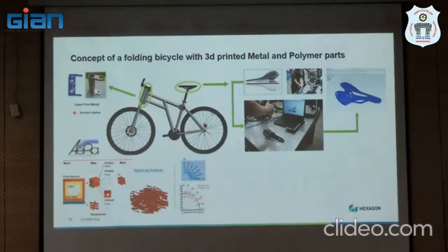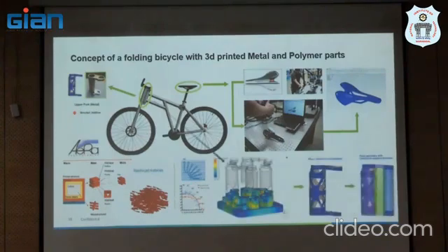But for metal, still a lot of justification has to be provided. For composite, it's very easy. You know the unidirectional and bidirectional strength. You can develop your own composite material based on the application requirement. You know the passenger weight, you know the dimension. Now you develop your own composite material and give it to them. That can be done easily.